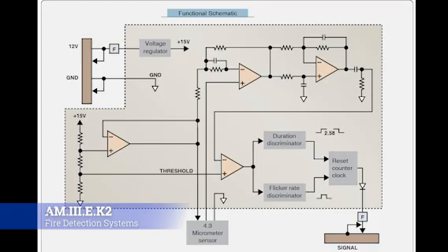The radiation striking the sensing device minutely raises the temperature, causing small thermoelectric voltages to be generated. These voltages are fed to an amplifier whose output is connected with the various analytical electronic processing circuits. The processing electronics is tailored exactly to the time signature of all the known hydrocarbon flame sources and ignores false alarm sources such as incandescent lights, light bulbs and sunlight. Alarm sensitivity level is accurately controlled by the digital circuit, and a typical warning is illustrated here in front of you. Now, that's a long way to say that essentially what happens is that a fire is going to emit a certain type of light.